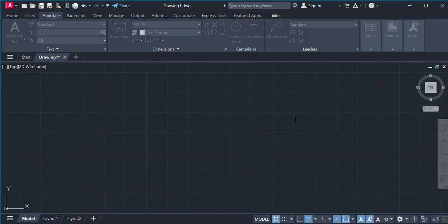Okay. So the reason we click on annotative, you want to make sure that regardless of the size of the object you're drawing, you're still able to see the text of your dimensions or the text that you will be typing on your actual drawing. Then leave the effects. You don't want it upside down. You don't want it backwards. Your width factor, you can leave it as 1. Oblique angle as 0. You want your work to be straight. Okay. Then you are gonna apply, then set current, and then you close. Then that's it for the text, right?